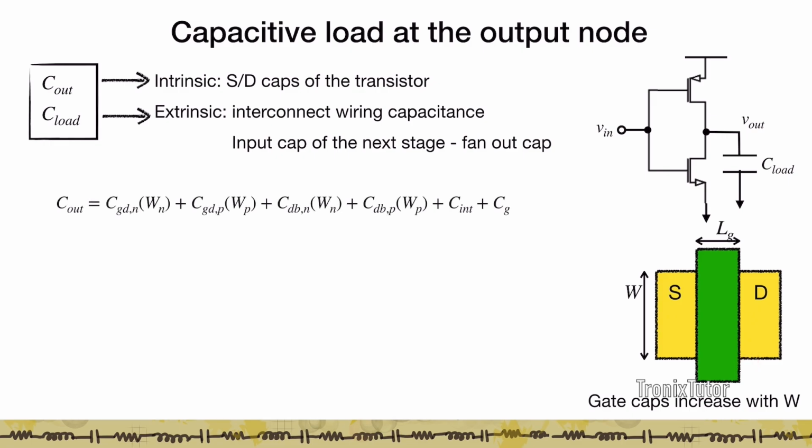Why am I thinking about this? Remember, when I want to speed up the circuit, one easy way is to increase the size of these transistors, right? If I make this transistor W larger, then for the same voltage I can pull a lot more current through the transistor. So I can trade off speed with area in such a case, right? While the transistors will be larger, I'd be able to make the inverter switch faster.